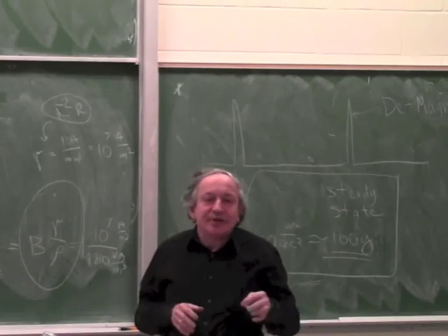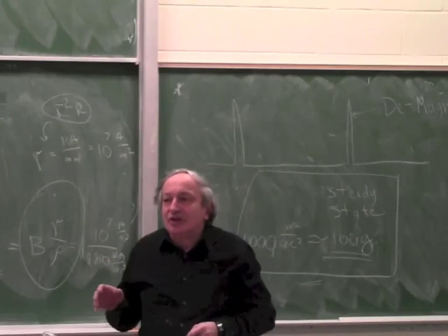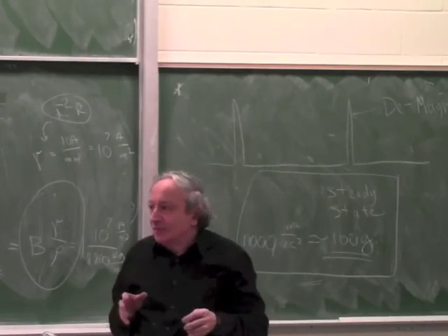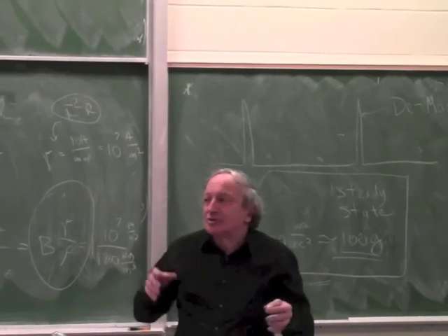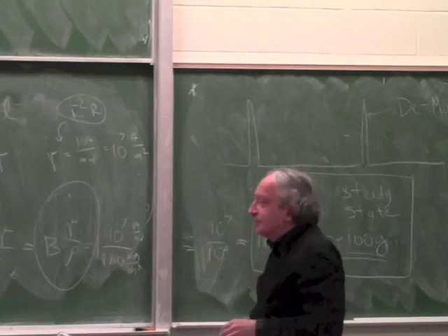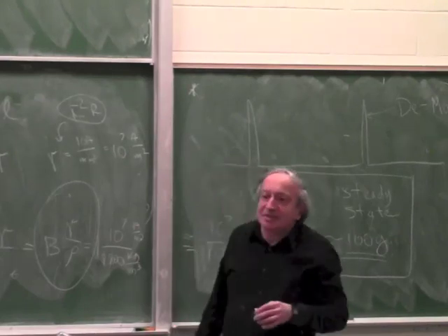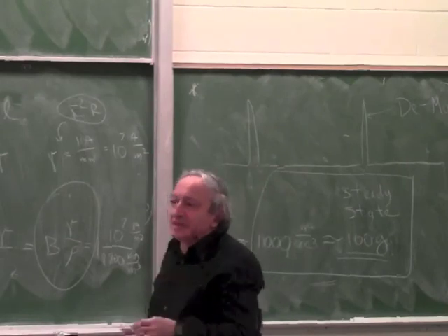As you know, different copper alloys conduct differently, but there is a standard copper alloy used for making coils. It's called oxygen-free copper, and this copper conducts 90% of silver. So all the coils you see are all made from this copper. It's called oxygen-free copper. Because strangely enough in metals, just a teeny bit of alloying element kills electrical conductivity